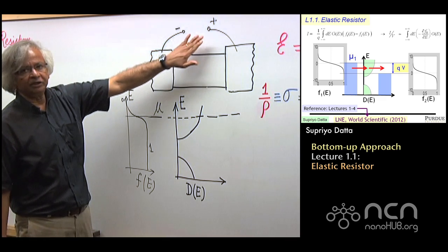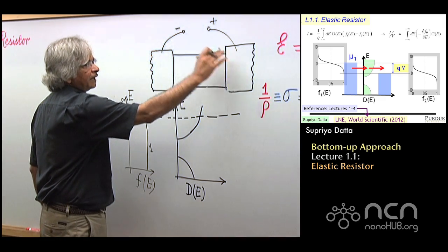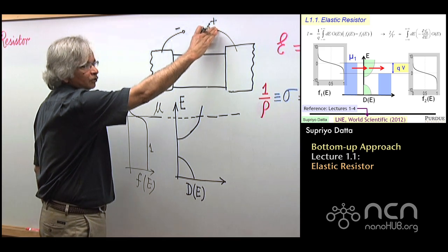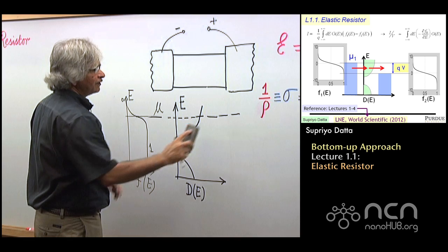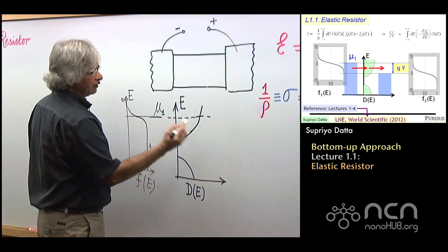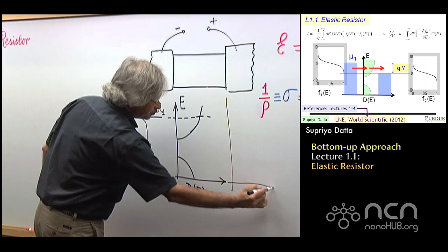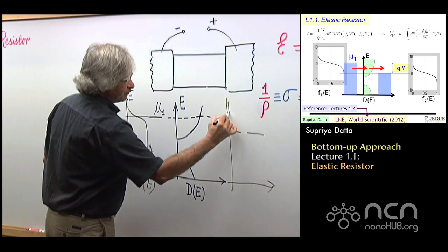And at equilibrium, we have the same Fermi function everywhere. Now, when you apply a voltage across it, that's a battery, then the right-hand contact, assuming we have a positive voltage on it, everything here is pulled down. And so we have a different chemical potential. So I'll call this mu1, and this is a different one, which we'll call mu2. And we have a different Fermi function here.